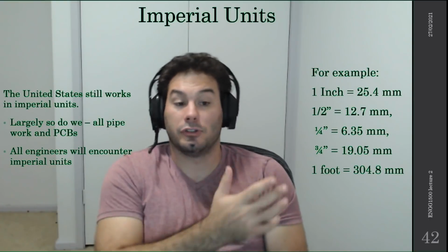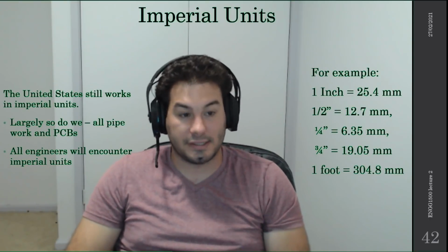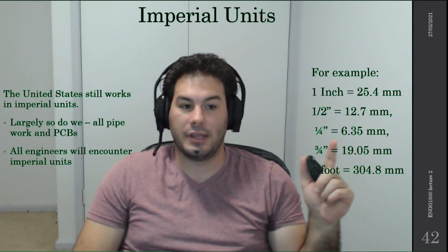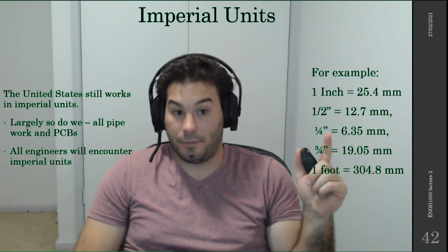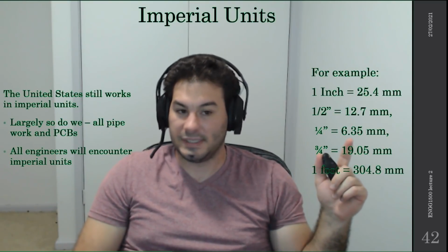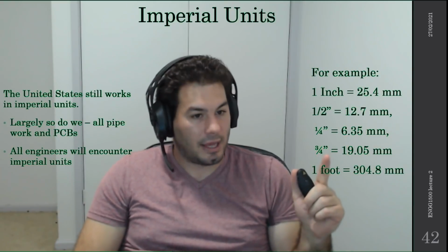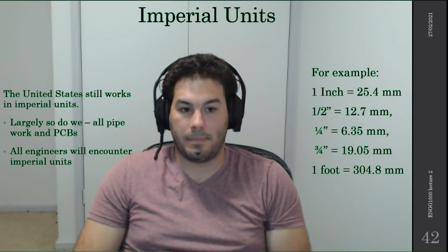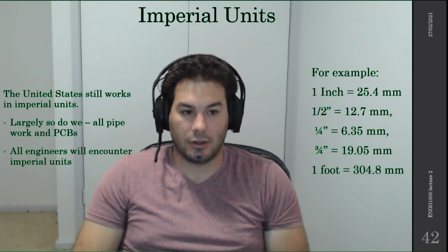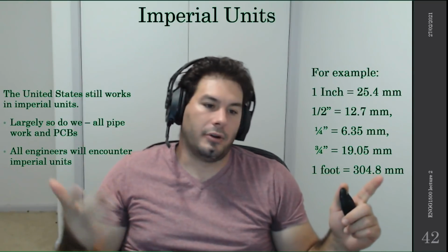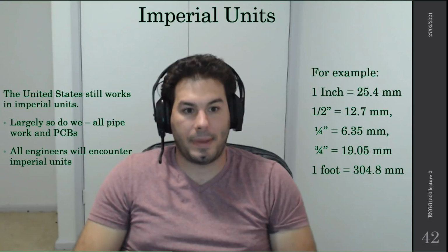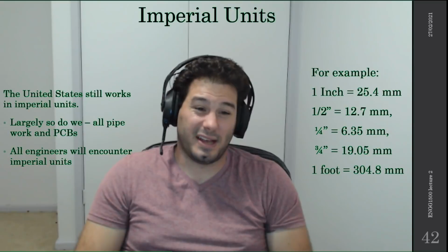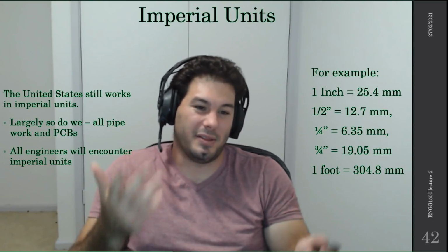So an inch, these are the most common ones. An inch is 25.4 millimeters. A half inch is 12.7. A quarter is 6.35. So you're in danger zone here, because sometimes you'll get stuff that will fit quarter and won't fit 6. So this can be tricky. As I said, 3/4 is almost bang on 19, and 5/8 is almost bang on 16. They're really close. A foot, 12 inches, 305-ish mil. A pound, 2.2 pounds to a kilo is another super useful one. So you got to do pounds and kilos, just halve it or double it, and you're there or thereabouts.